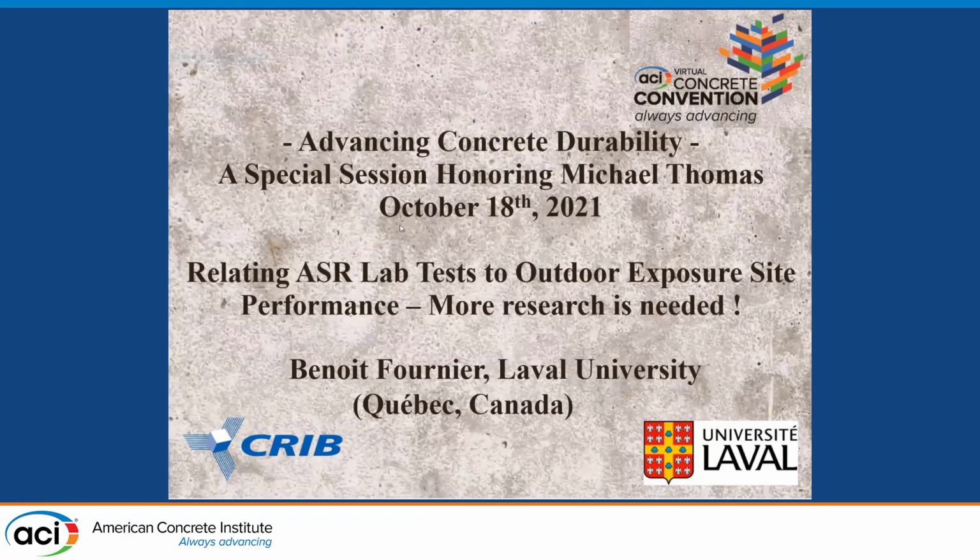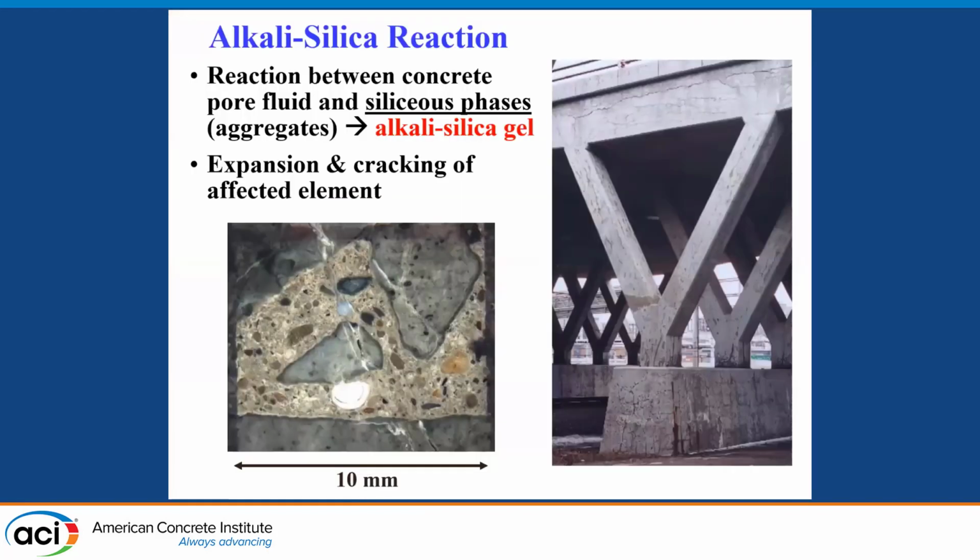As was said, the talk will be relating ASR lab test to outdoor exposure site. So we have heard from Karen that ASR is indeed a chemical reaction between reactive aggregate particles and the pore solution of the concrete that results in the formation of a secondary alkali-silica gel that will create pressure, expansion, and cracking of the affected element.